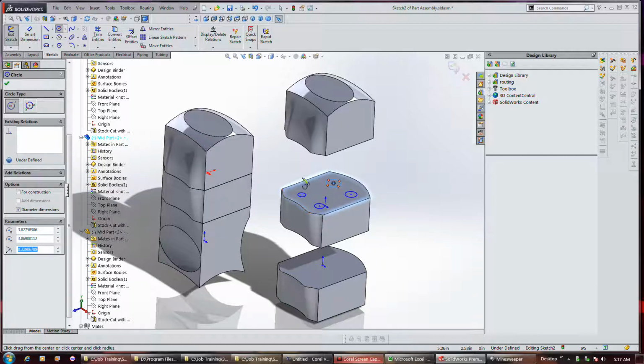You should actually create them on an independent plane that's not connected to any of these parts. It's not dependent on it, otherwise you can create circular dependencies and things like that, which would be a problem if any of these parts changed. It could actually get haywire.